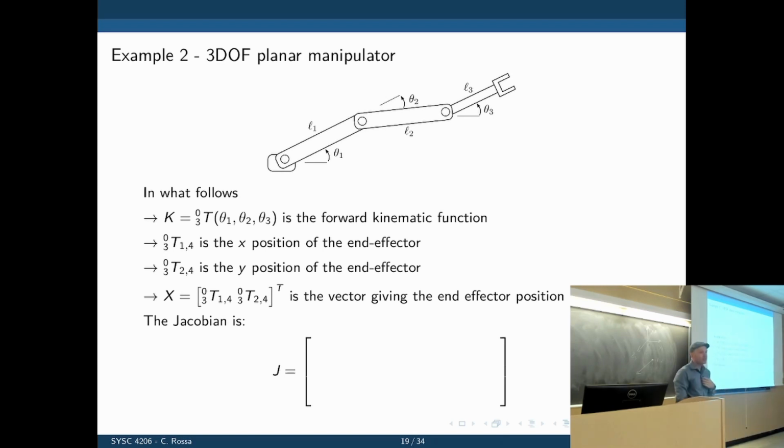I'll define the problem. Find the suitable values for θ1, θ2, and θ3 that will bring the end effector to a specific position without the inverse kinematics. First of all, find the transformation matrices. Find the forward kinematics equation using the transformation matrices.